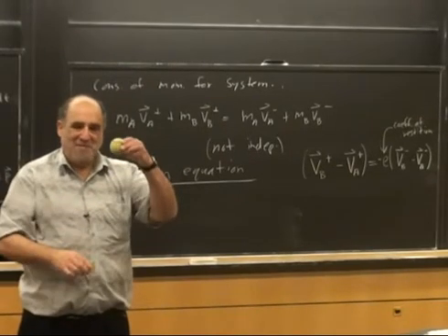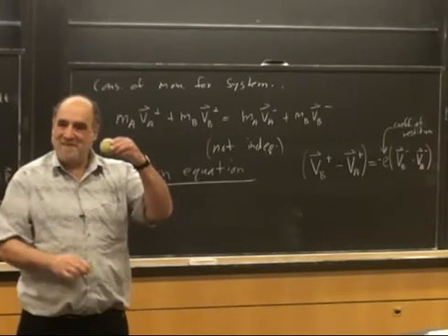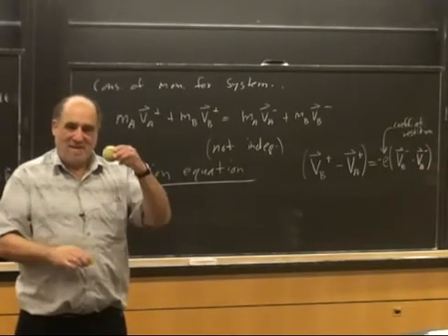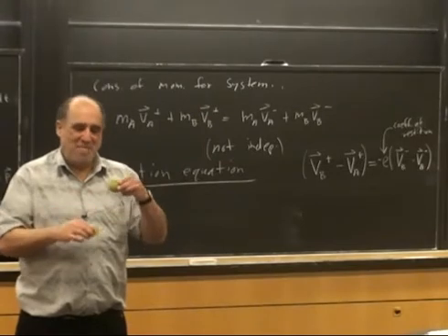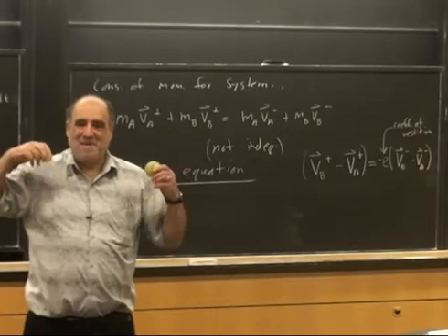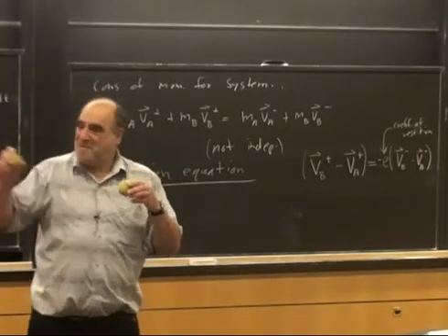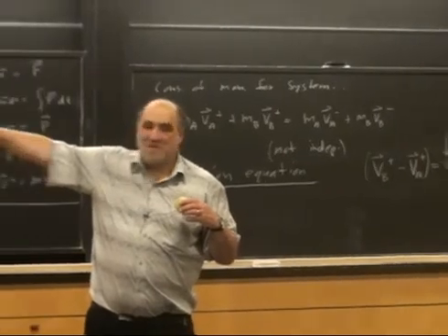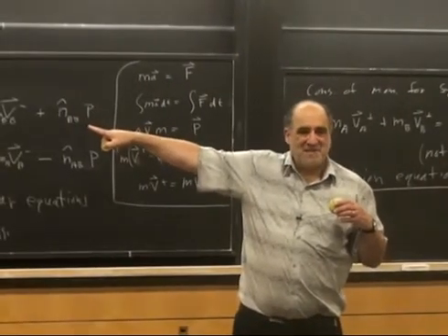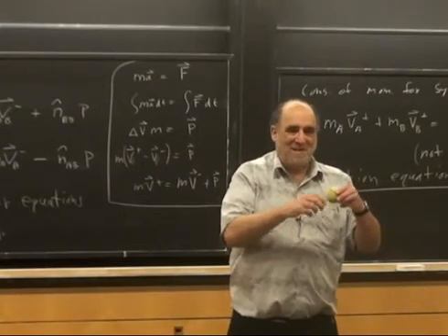If I said the velocity is reversed, I would get a collision like this, where they hit like this and they bounce back. Which obviously doesn't happen, right? The most that could happen is they start spinning, but I don't even have spinning in here. I'm kind of living in a particle world, even though I've drawn balls. And I also said on the board, we're assuming no friction for this collision calculation. So the collision is not about reversing of tangential velocity.